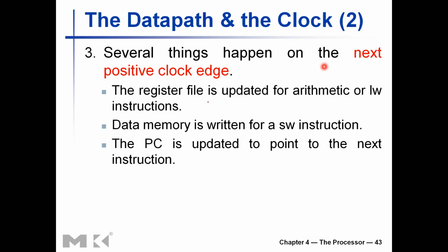and that is the same thing as at the end of this clock cycle, we'll also be updating the program counter. That may be PC plus 4, PC plus 4 plus branch offset, branch target, or PC plus 4 plus the jump target. So whatever the instruction was, the correct value should be written to the program counter, and that writing will happen at the positive clock edge. So every positive clock edge of the clock cycle, the program counter will be updated, and the data memory or register file is also written to. So this process repeats, right?